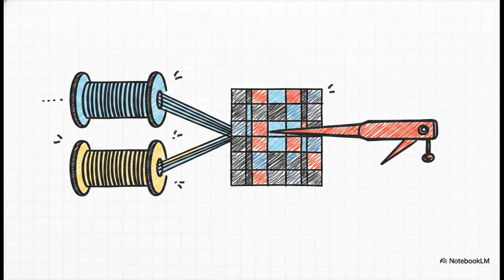Knowing our boundaries is great, but the computer needs physical coordinates to actually calculate the math. So by passing our boundary limits into the linspace function and then feeding that right into the meshgrid command, we're essentially rolling out this massive sheet of digital graph paper across the x and z axes. That meshgrid command takes those 1D lines and weaves them together into a 2D grid. So now we have an arena, a specific set of coordinates where our physics simulation can actually take place.